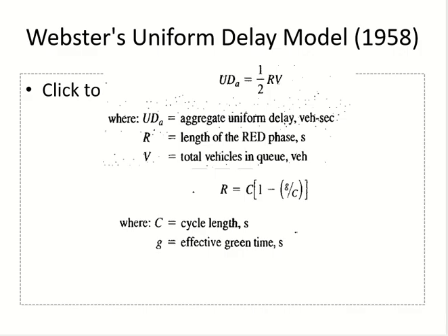We are designing time for the movement of vehicles, and movement of vehicles happens during green time. So whatever is not green is basically red time. Now this is a very special type of green. We will not go into details, but this green basically involves everything, the yellow time and all that. This is not just the green light. That's why we can use this equation, and whatever it's saying is true: whatever is not green, 1 minus.